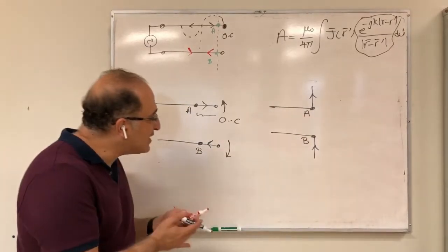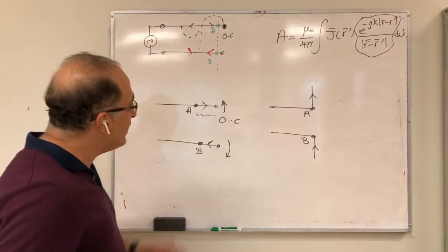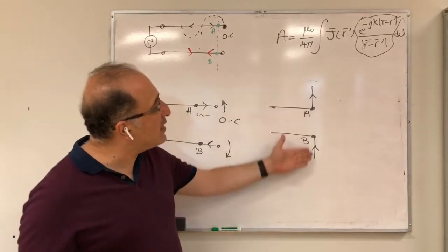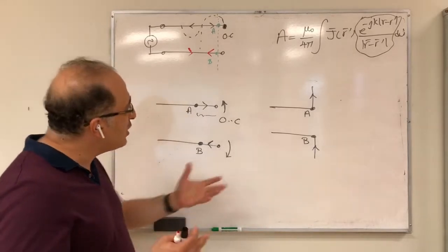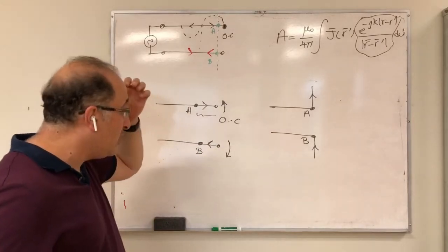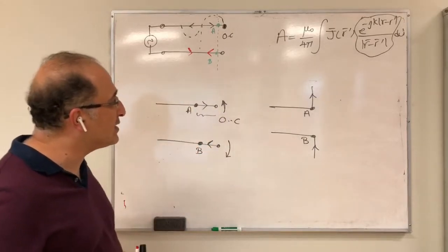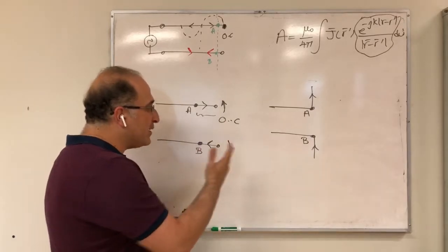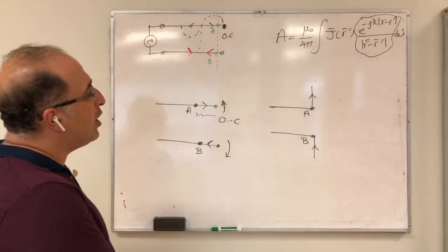Now, of course, as you realize here, this is the current in the open-ended transmission line. If you bend it, the current might change, but it has been shown that you can assume the current stays relatively the same, so you can essentially use that. But remember that if you do something to the transmission line, you cannot automatically assume that everything is the same and it's just the direction of the current that's changing. But here we assume that this approximation is acceptable. So that's our dipole antenna.